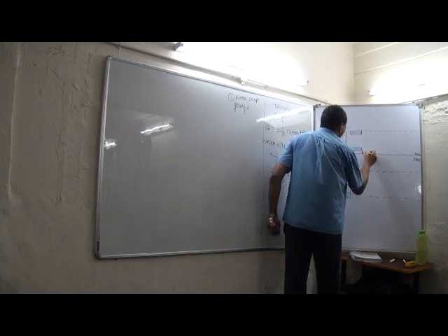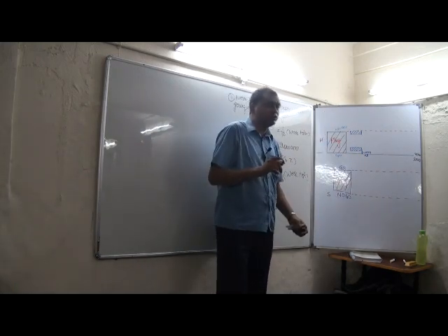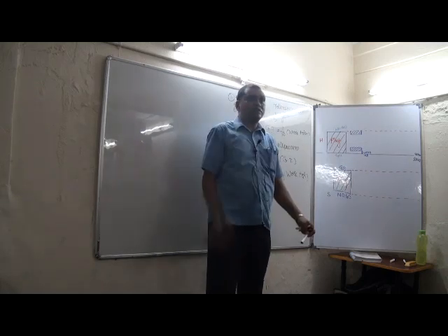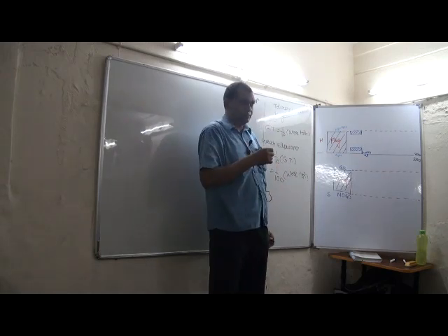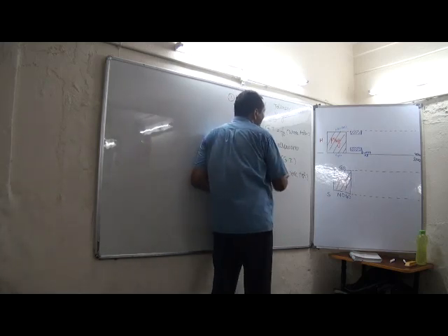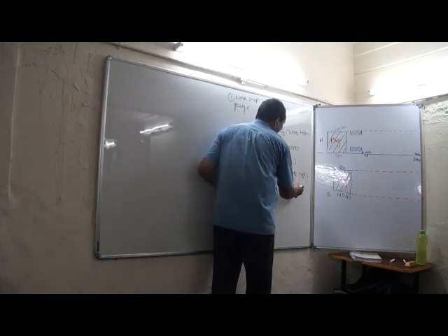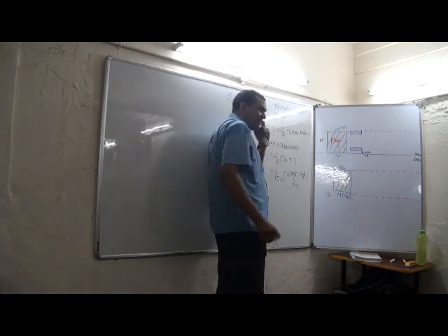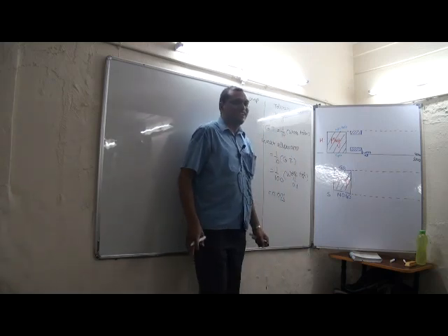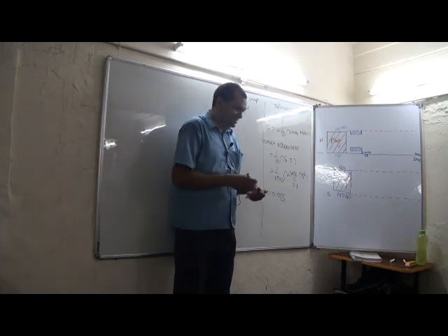See, this is the wear allowance. Why do we give the wear allowance to the go gauge? To increase its life, because every time the go gauge is moving in and out, there will be wear on it. So we have to give the wear allowance. But remember that the wear allowance is 1/100 of the work tolerance. So when the work tolerance is almost 0.1, then the wear allowance will be 0.001, which is very difficult to provide. Is it enough? 1 micron is very insignificant.